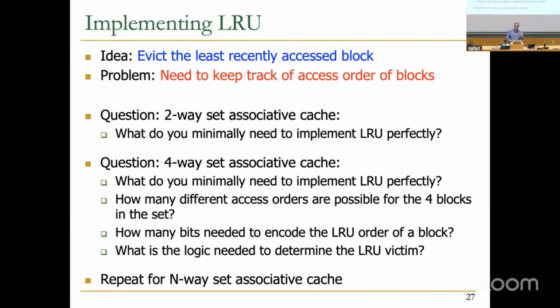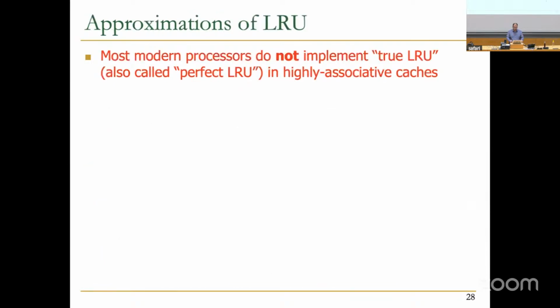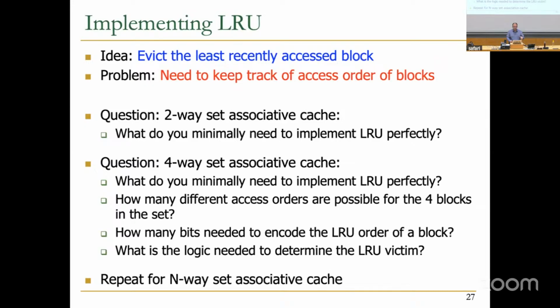Yeah, number of blocks times log n, exactly. Number of blocks times log n, that can actually simplify the logic that you have for that. But as a conclusion, unfortunately I don't have enough time, you can see that implementing LRU is actually costly in terms of storage space and also in terms of the logic that you need to add. Specifically when you have a lot of ways.